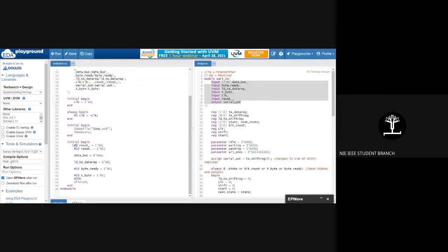Coming to the reset, I first reset after, let's say, some 2 time units. You can either remove it or it's just there. Timing, you can take care of by yourself. You can play around with numbers. When I pull the reset low, that's when reset gets activated. The whole state machine gets deactivated. It just stops, flushes with 1, bit count gets 0, start, shift, everything gets 0. That's what we discussed.